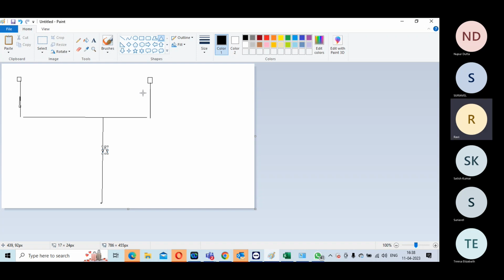Will you throw it? Because there's functional failure. So what will you do? How will you use this? That was the question. If there's a setup violation, you can run it at a lesser frequency. If there's a hold violation, what will you do? Functional failure. How do you make it functionally pass? That's the question, right?